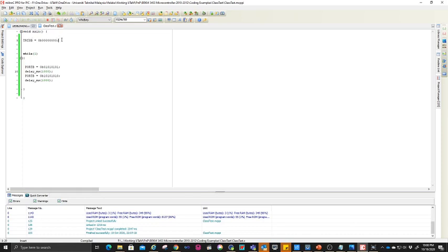If you want to play around with port D, you're going to use TRISD, and then TRISA, and TRISC, something like that. So you're going to set up again like this. It's up to you how you want to set up. Okay, this is how you set up, then you can play around with this.